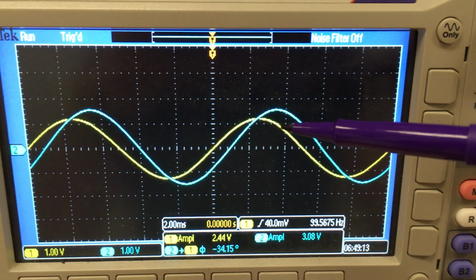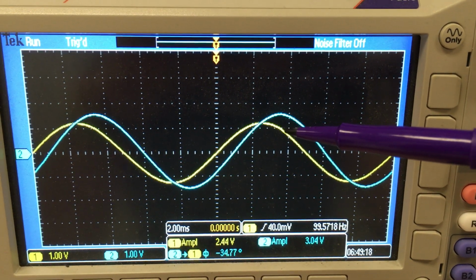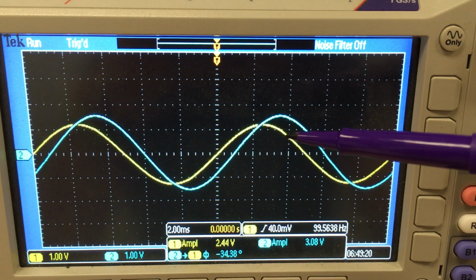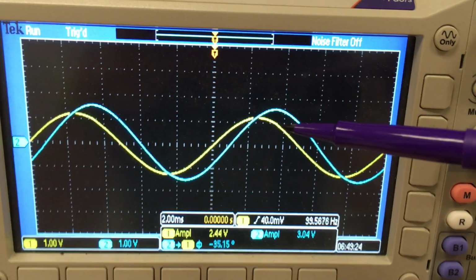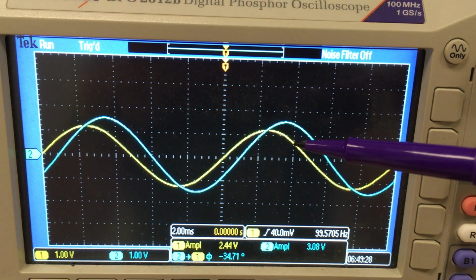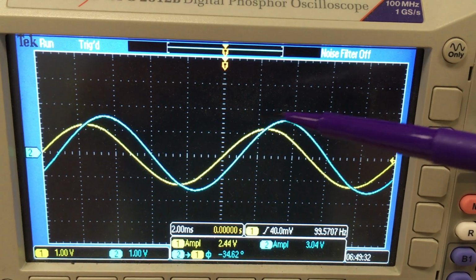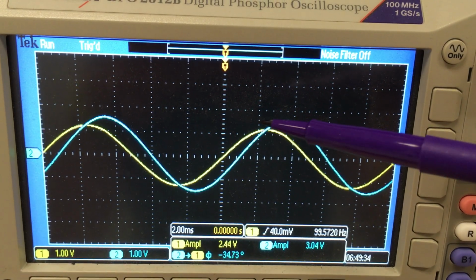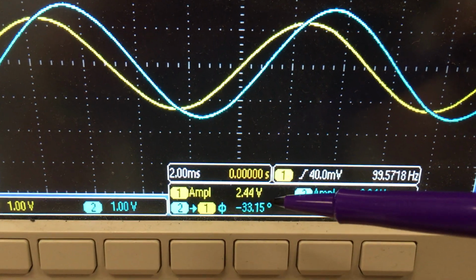Okay? And this offset is because of the capacitor alternately storing up and releasing its charges, and thus its electrical energy. If we had no capacitor in our circuit, if we just had the resistor, well then we would have these two waves being exactly in phase. In other words, none of this little offset in time. They usually measure phase differences in terms of an angle.